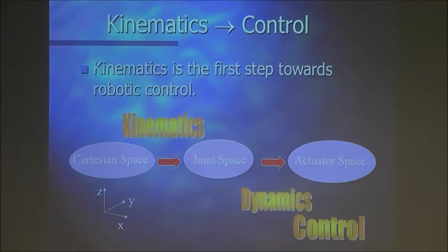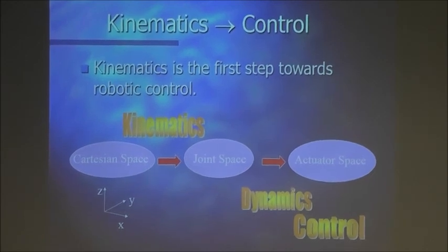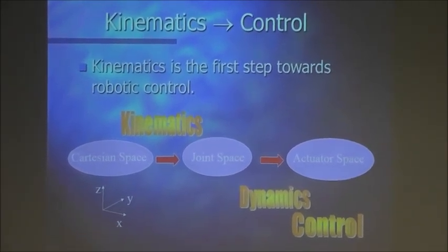It may be that because you have a highly nonlinear environment, you have to linearize the model of the robot around its own workspace, to be approximately acting linearly. Do your design in the linear model, then go back and apply it to the actual robot in a nonlinear situation.